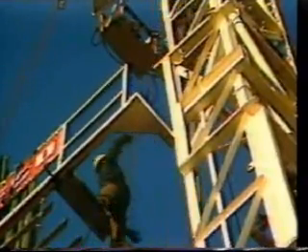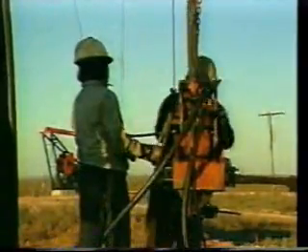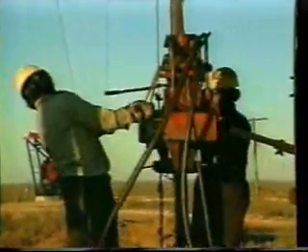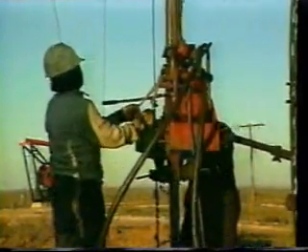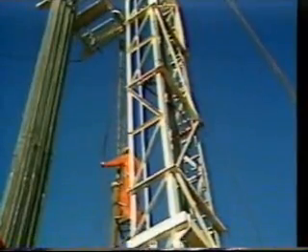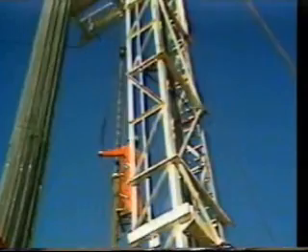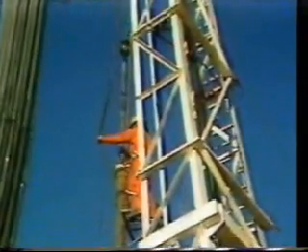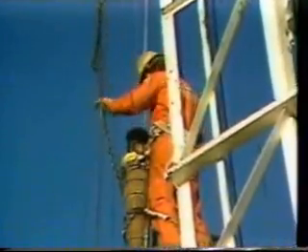Whichever completion rig is used, the tubing must be measured into the hole and the drilling fluid circulated out. Perforating should be done with a clean, solids-free fluid in the hole if possible. If perforating is done at this time, the tubing is removed and the perforating gun is lowered and positioned according to the casing collars on the correlation log. The gun is fired and retrieved.